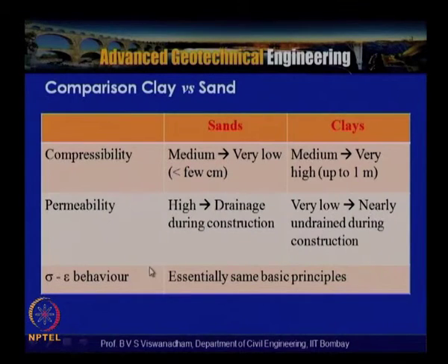If you look into the stress strain behavior for sands and clays, essentially the same basic principles are applied. So we have to note here that sands have high permeability and drainage happens during construction, and clays have very low permeability and behave nearly undrained during construction.